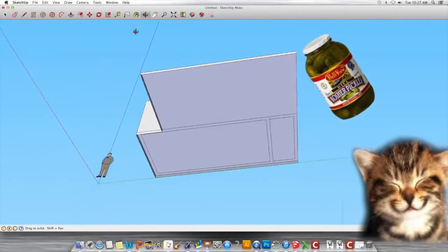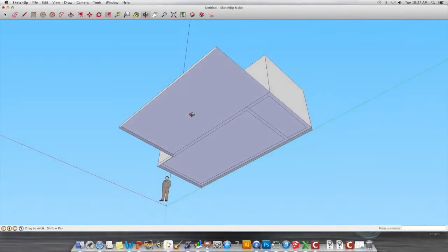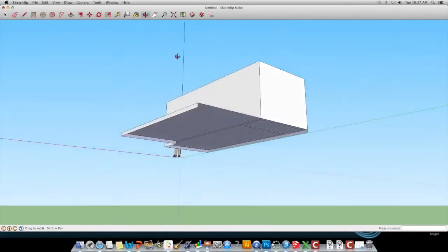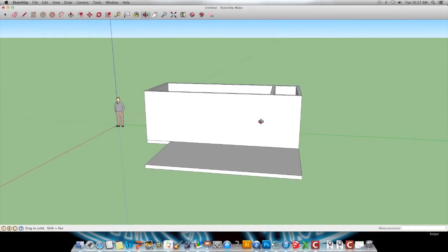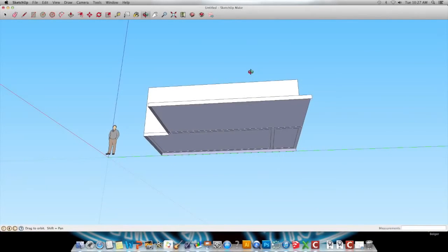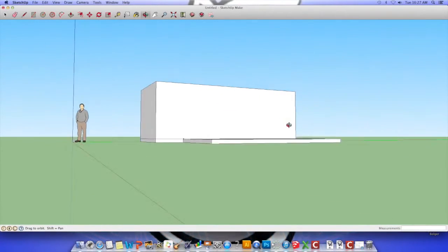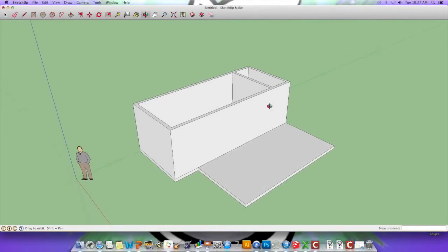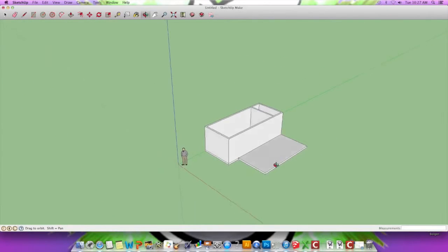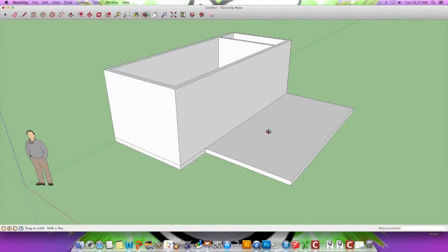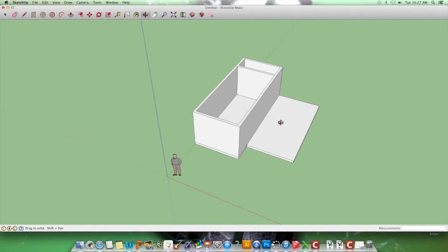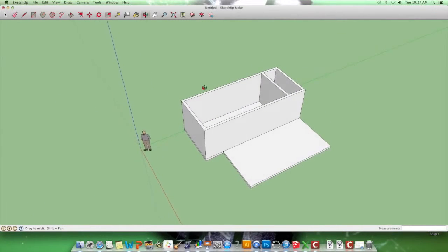So now later on when I flip, and let's say I did like 3 more rooms thinking that everything was okay, and then I realized this, it's going to cause major problems for me later. So I'm going to Command Z those actions, okay, and make sure that it's right. If you erase something and you notice something's missing, Command Z it right away, because you don't want to Command Z the entire room that you just made. You want to Command Z it as soon as you make the mistake. If you don't notice the mistake, it's going to be a problem. So look around. I don't want you to have to do things over. I want you to do them right the first time.